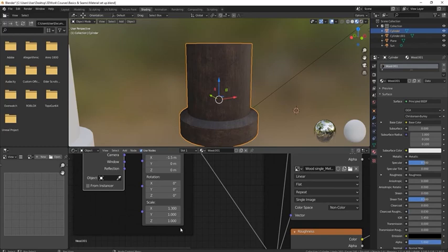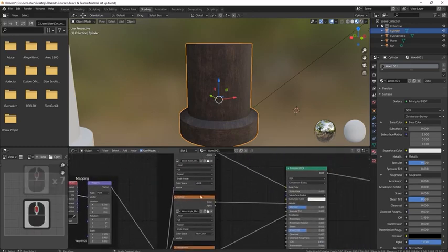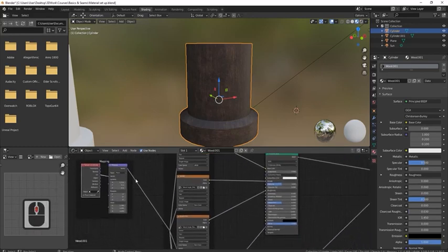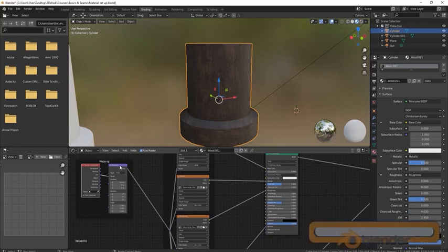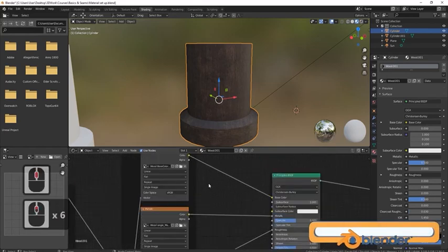It gives you a lot of control within the shader to mess around with the scale and things like that. Normally, I would do this in the UV map, but if there are any small details that I want to make a little bit smaller or something like that, I will do it within the shader. Moving across, you can see that all of these nodes over here, which are our maps, are plugged into our mapping node. So let's come to the first one.